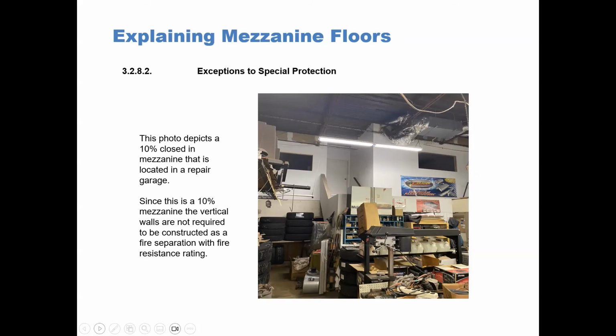This photograph depicts a 10% closed-in mezzanine that's located in a repair garage. Since this is a 10% mezzanine, the vertical walls that you see in the photograph are not required to be constructed as a fire separation with a fire resistance rating.